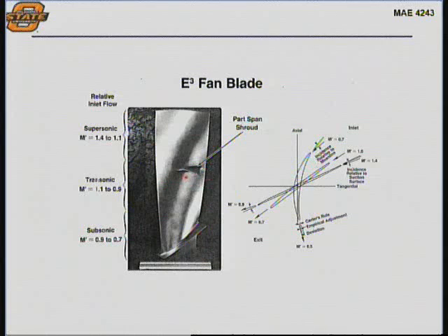Somewhere near the midspan, you have this middle airfoil shape here. Notice that it's much thinner. Its max thickness is much different than it is at the hub. One of the main reasons is that you're moving much faster. Here you're moving basically sonic and transonic. I want to have as minimal area as possible into the flow. And then near the tip, where you're definitely supersonic, you can see a certainly different stagger angle, and you have a very thin, very small max thickness airfoil.